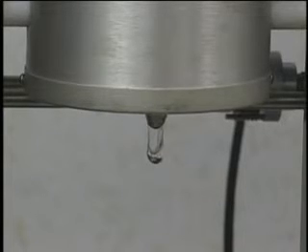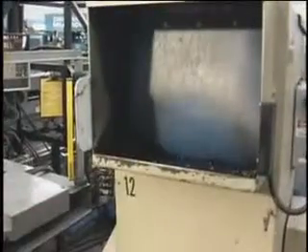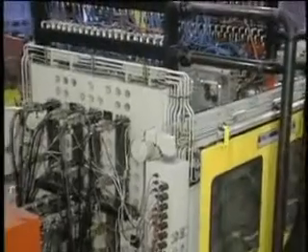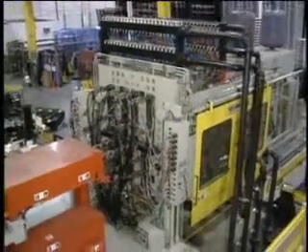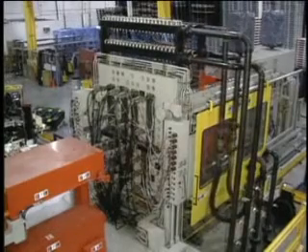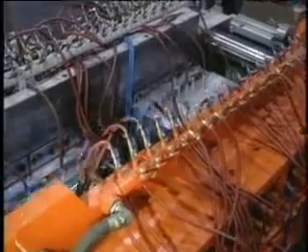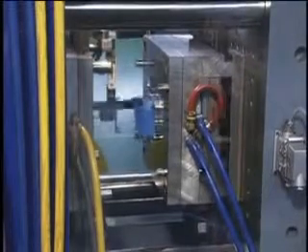Thermoplastics undergo a reversible change from solid to liquid when heated, and can be cooled and reground for reuse over and over again. Thermosets undergo a chemical reaction between two reagents when heated and achieve their strength through interlocking chemical bonds. Once molded, thermosets cannot be resoftened. While thermosets are injection moldable, most materials used in injection molding machines are thermoplastics.